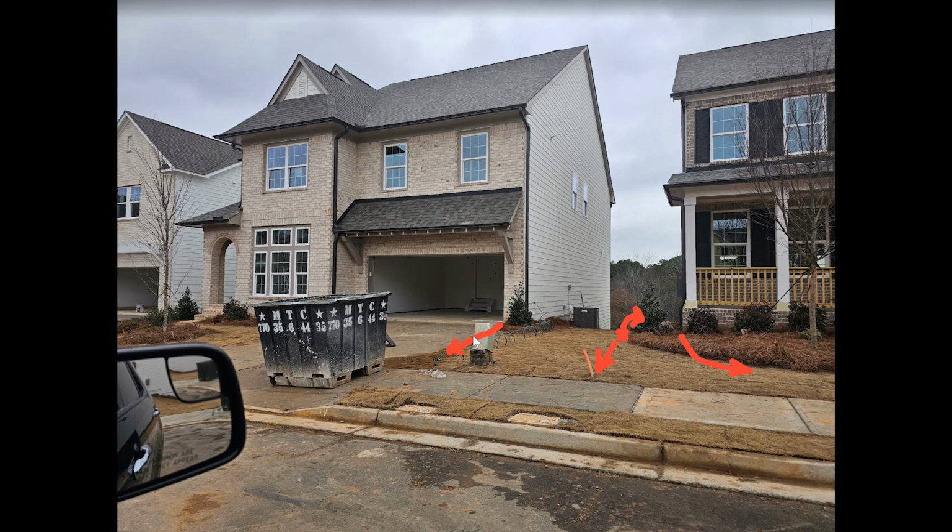And as we put the contours in, we've got that little hill that comes off of the garage. And if we extended that out, it would follow the house going around. But when we draw these in, at least at the house there, we don't continue the contour around the house. We just dead end it into the house in a perpendicular fashion. And here I'm just finishing out the contours.